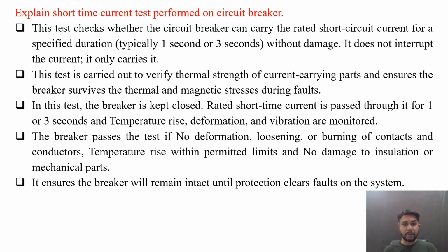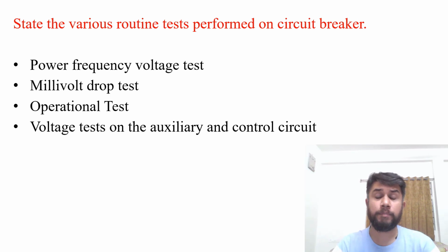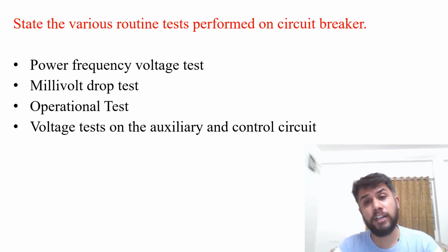It ensures the breaker will remain intact until the protection clears fault on the system. So this is all about the short time current test performed on circuit breaker. State the various routine tests performed on circuit breaker. Some of these are power frequency voltage test, millivolt drop test, operational test, voltage test on the auxiliary and control.